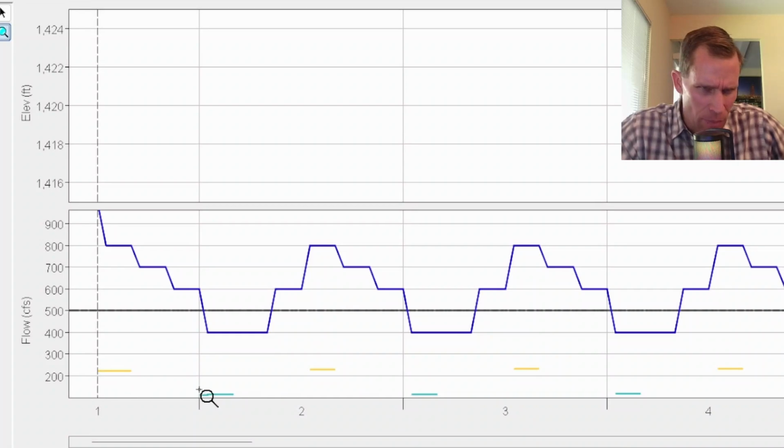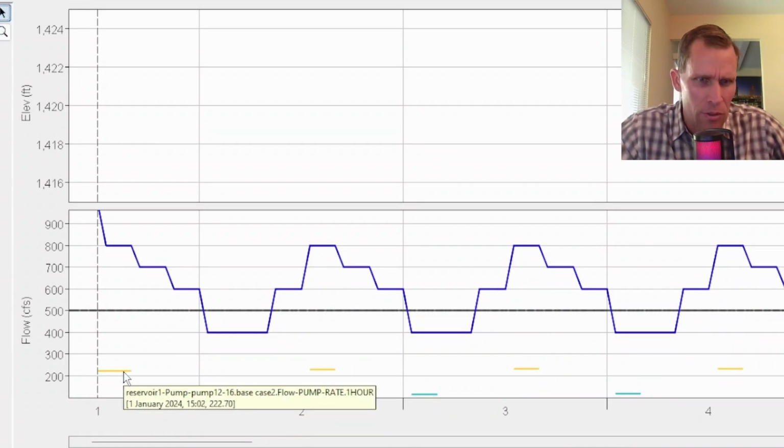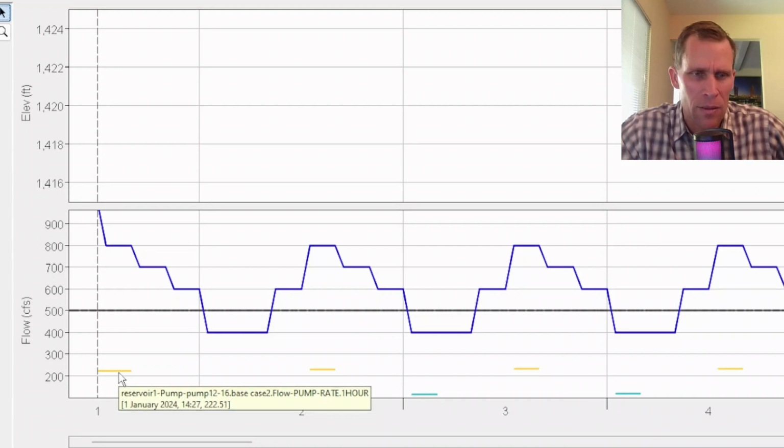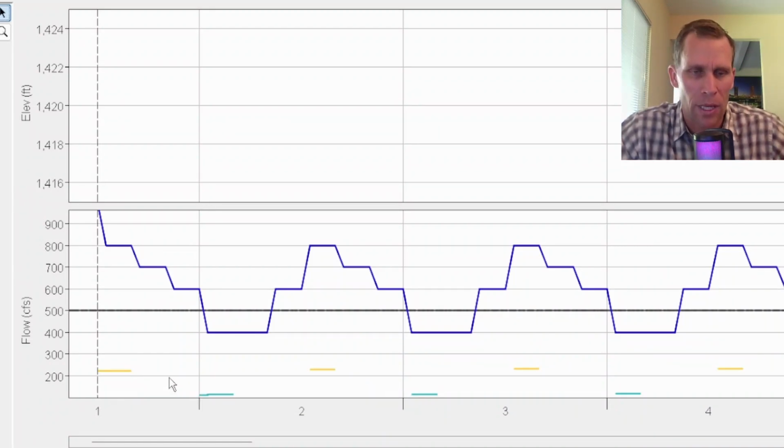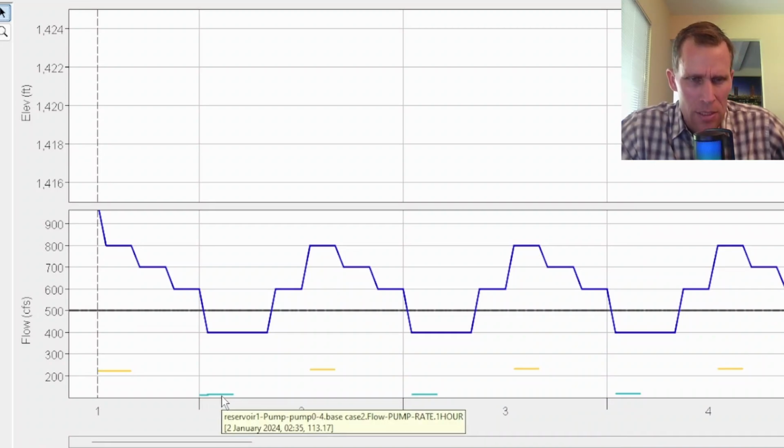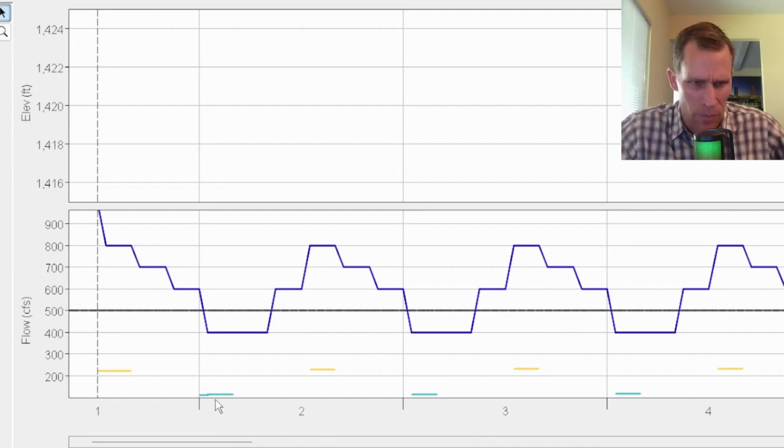And you can see barely, click on the arrow pencil here. So it looks like, yeah, we have about 222 CFS of pumping. That's for the first 4 hours in the afternoon from noon to 4 p.m. And then down here we have about 113 CFS of pumping. That's 1 pump operating from midnight to 4 a.m. So let's see here. Here's the yellow line. You can see it a little bit easier there. And then here's for 2 pumps. This is the blue line for 1 pump.